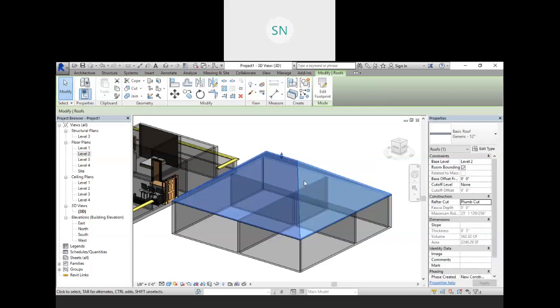So we do not have a proper option for that. There must be. Okay, fine. But let me discuss that define slope thing. Slope in properties, yes, it is over here. You can provide your values, for example 1 inch per 12 inch. So this is my minimum slope.